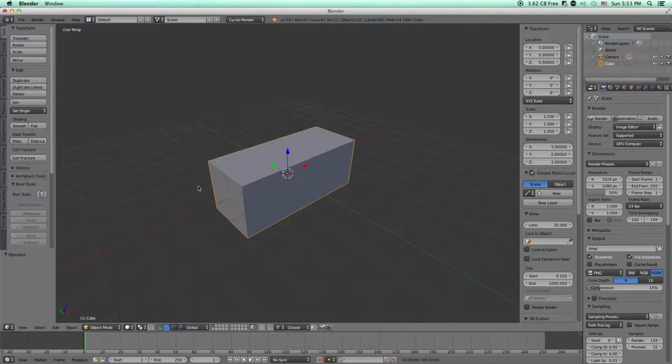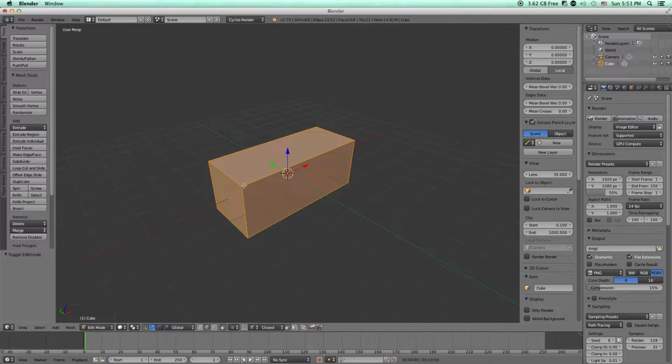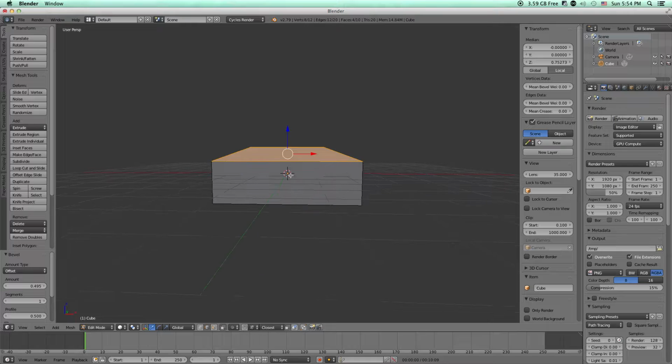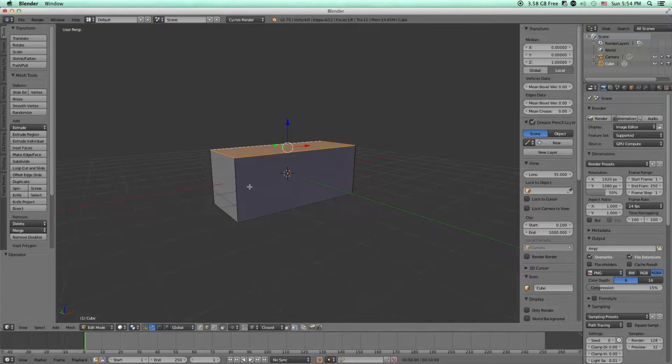And one of the issues we have, if we don't have our scale on 1:1, if I wanted to bevel, say, these 4 corners, and I do Control B and drag away from the center, it's not going to bevel properly. It's going to have different angles, which is maybe hard to tell on here, different angles.